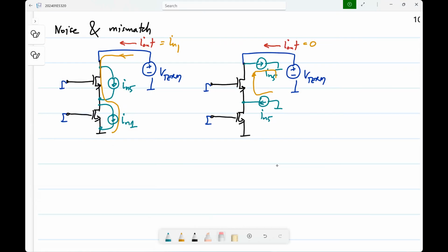Usually, circuit simulators provide a summary of the dominant noise contributors. So, from that you can see... Now, you shouldn't be surprised if you see that the cascode device is also contributing noise. Then you have to look at why it is contributing noise. It is possible, because we make so many approximations here, some of them may be violated in that case. Okay. Any questions?